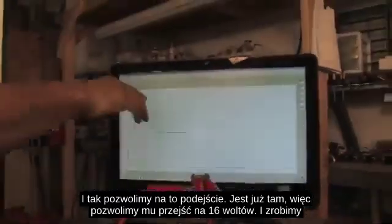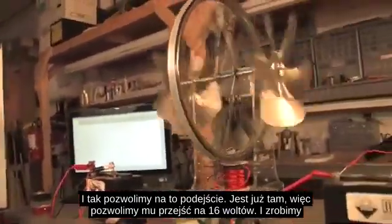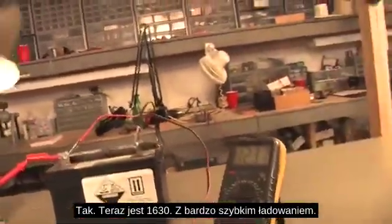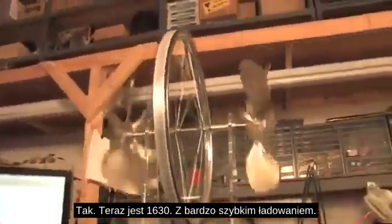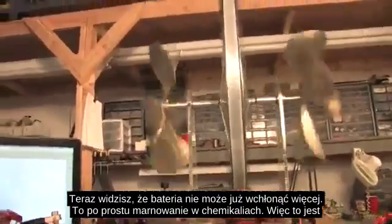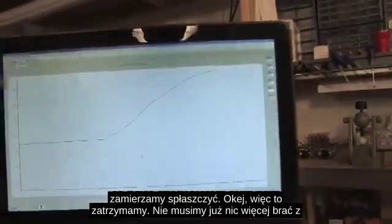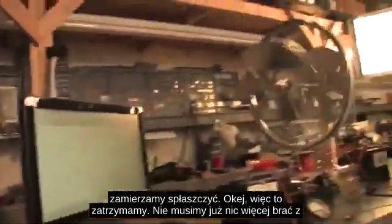And so we'll let this approach. It's already there, so we'll let it go to 16 volts, and we'll stop the charge. Is it 16 volts? Yeah, it's at 16.30, with a very quick charge. Now see, the battery can't absorb any more. It's just wasting in the chemical. So it's going to flatten out. Okay, so we'll stop this.